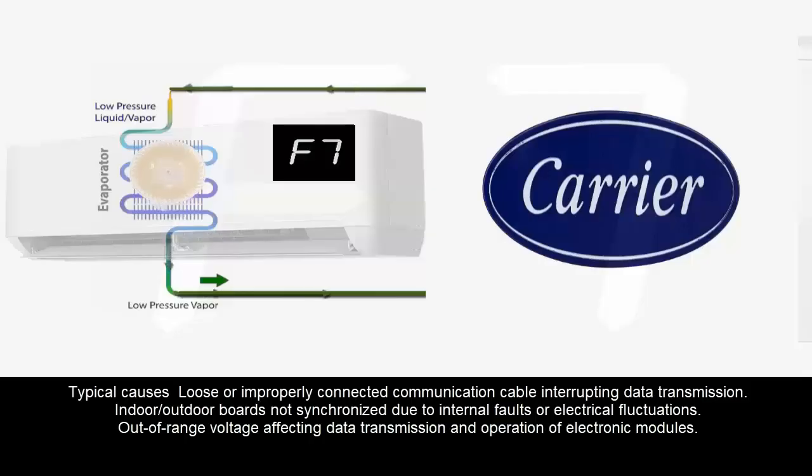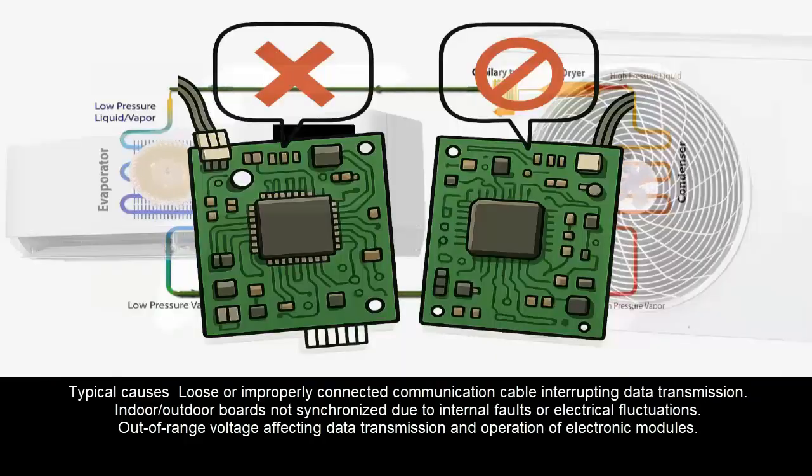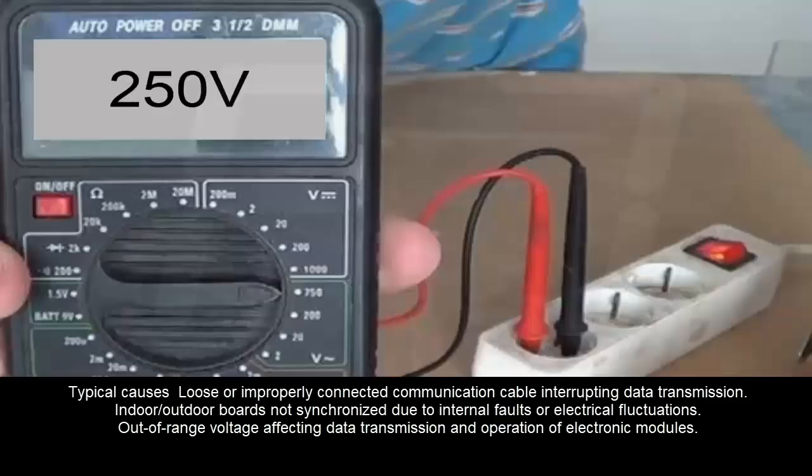Typical causes: loose or improperly connected communication cable interrupting data transmission. Indoor-outdoor boards not synchronized due to internal faults or electrical fluctuations. Out-of-range voltage affecting data transmission and operation of electronic modules.